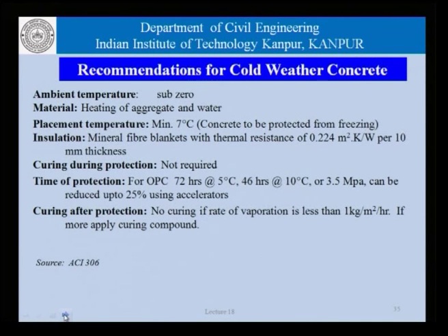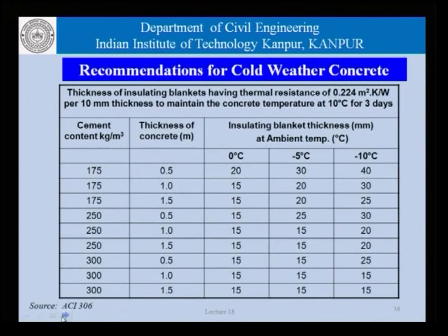When the temperatures are sub-zero, we may need to resort to not only heating water, but also the heating of aggregates in order that the concrete meets the minimum temperature. Similarly, we will probably need to have mineral fiber blankets for insulation of the concrete, and we can of course prescribe the time of protection in terms of time or in terms of strength, and talk in terms of the curing after the protection.